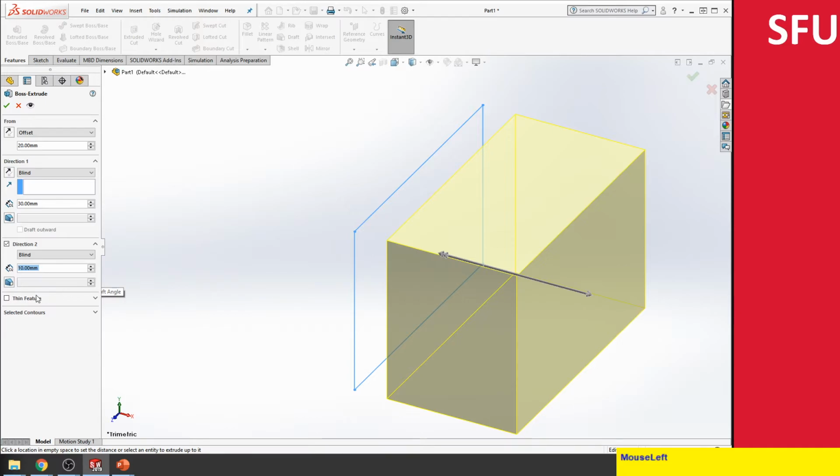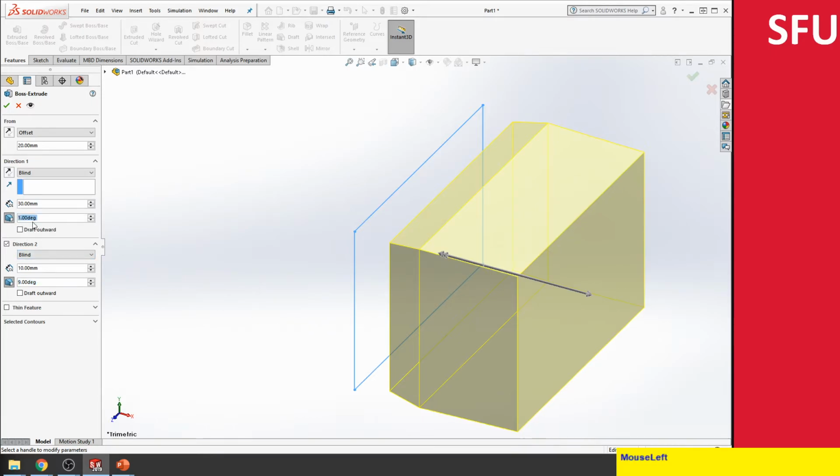What we mean by draft is that we are giving a small angle to the extrusion. Here I'm making it larger so that you can actually see. Right now I've given it 9 degrees. The advantage is that I can have two different drafts in either direction. I can make this go this way, or you can have the draft go in the opposite direction, which is called an outward draft. Typically you would have an inward draft.